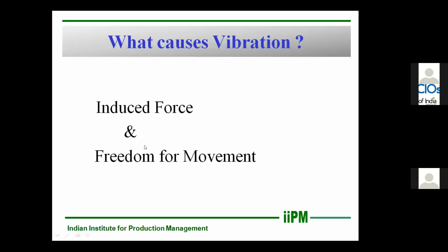So what causes vibration in the machine? Vibration is due to induced force and freedom for movement. Induced force is force generated within the machine. It can be due to unbalance, misalignment, or damaged bearing. These create some induced force in the machine due to which we can feel vibration.